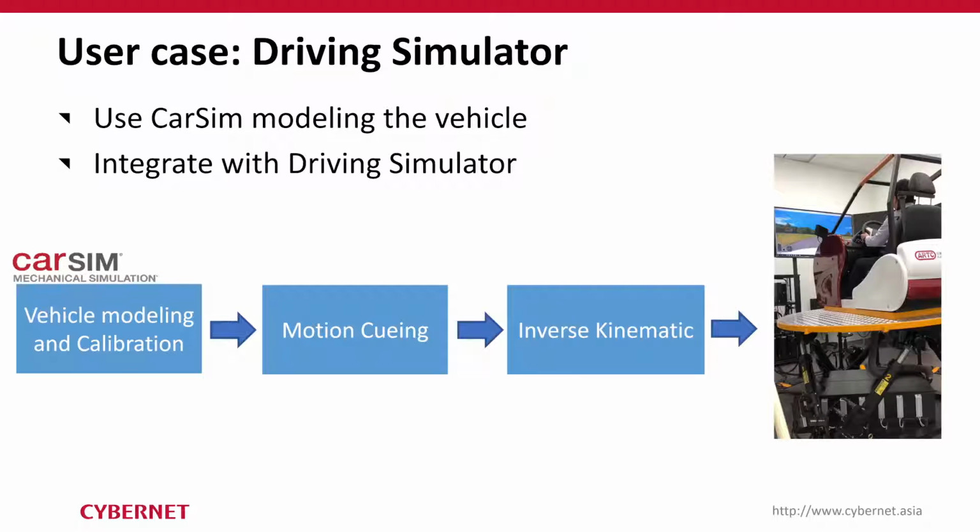The last example is the driving simulator. We built this driving simulator with CarSim RT, motion tuning, and a 6DOF motion platform. The motion tuning is going to implement the feeling of acceleration on the 6DOF motion platform. A real vehicle is running in an infinite world so that we will always have acceleration, velocity, and position changes. However, the motion platform works in a finite position.